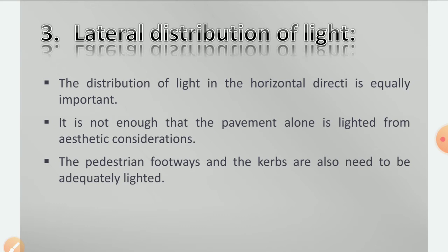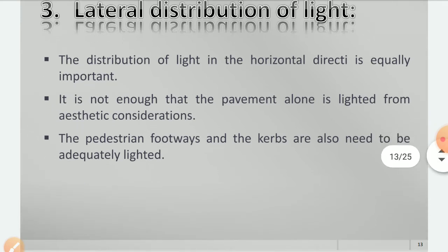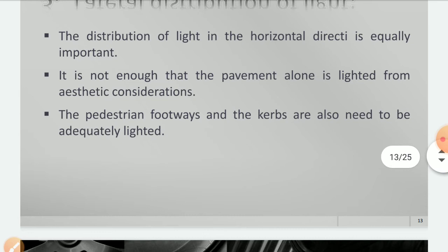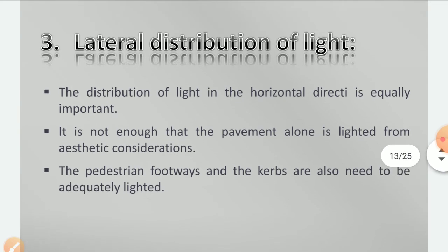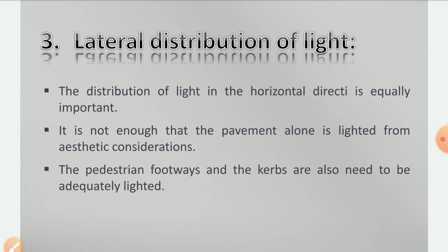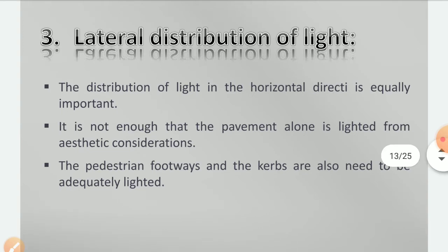Okay, so the pedestrians, those who are walking on the footpaths, the footways, also need to be adequately lighted. The purpose of street lighting is not only to serve the roads but also to serve the pedestrians. As well as the drivers, I mean vehicles, the pedestrians should also get a sufficient amount of illumination to walk through.